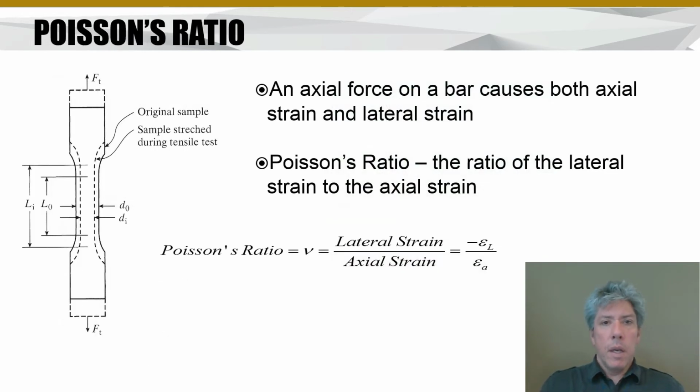Now, if you think about what happens when you stretch material, most materials are pretty much incompressible. What do I mean when I say incompressible? Well, you can say, wait a second, don't they stretch? I thought you just said they stretched. Well, there's a difference between stretching or straining and being incompressible or compressible. Compressibility has to do with how much the volume of something changes, not so much that its dimensions change.